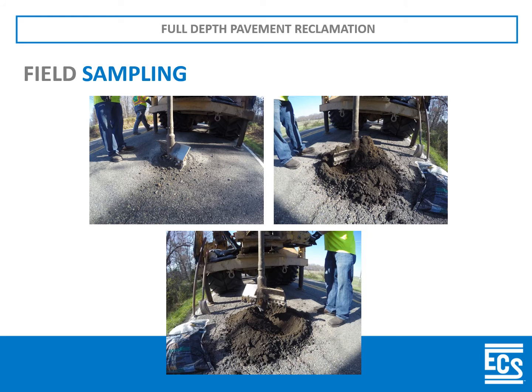And here are a couple of photos of the blending process. Basically, once you get through the asphalt, you go to the correct depth that's easily measured, and you just let the head rotate and turn for a couple of seconds as it blends the material for you. Then you just collect the samples, bring them back in buckets, patch the hole, and you're done.